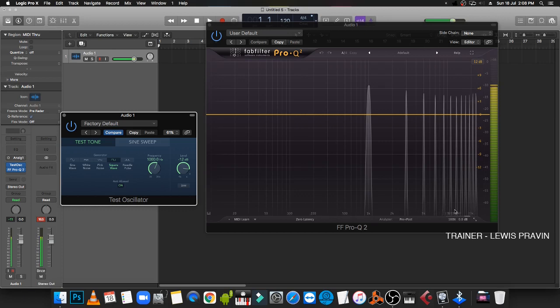All these extra frequencies seen on the graph are multiples of odd numbers. If you go to a sawtooth wave, you will see both odd and even. This particular tone generator does not have a sawtooth wave, but if it had, you would see 1000, 2000, 3000, 4000, 5000.